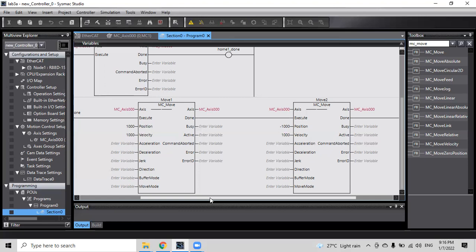This part is the smooth factor. It's also called jerk. We need to smooth out these two sharp angles here to make sure the connection between the acceleration and the cruising constant speed is smooth. Then we need to adjust the jerk to make sure the transient is smooth. That's why for the Move function block, you have acceleration, deceleration, and then jerk. Okay, now you understand that?